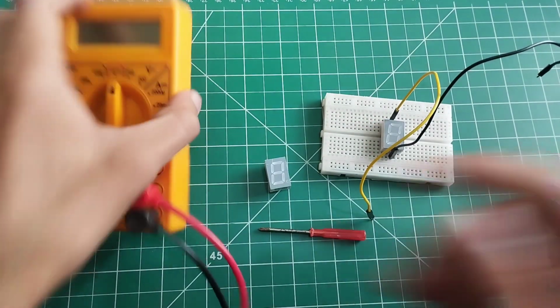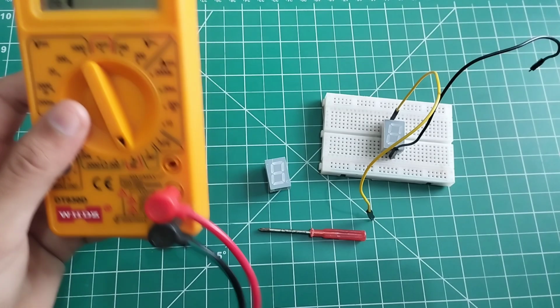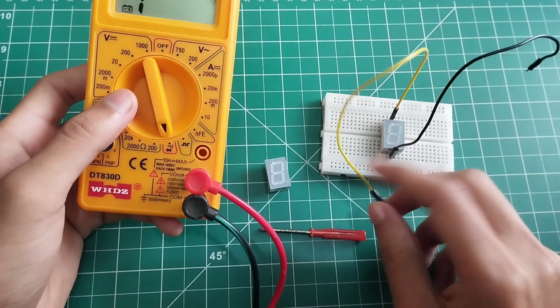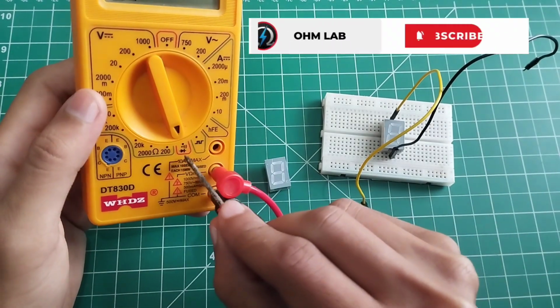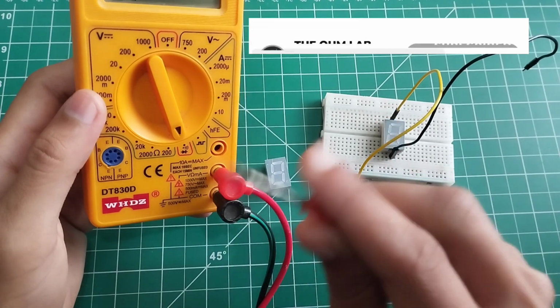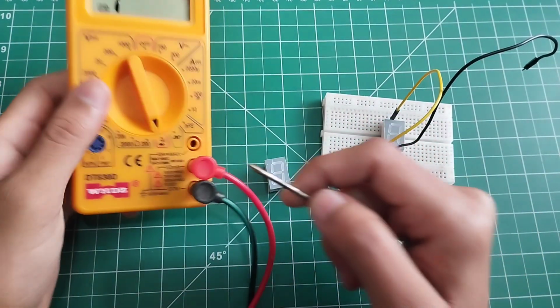And this is the multimeter. If I set the mode of this multimeter to the continuity mode, you will see that when I touch the probes of the multimeter to these wires, the buzzer will beep. You can see there are two symbols here. This is the diode mode and this is the continuity mode. So with this mode you can check two things. The first one is continuity and the other one is you can also test a diode.